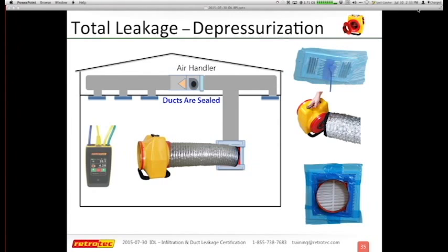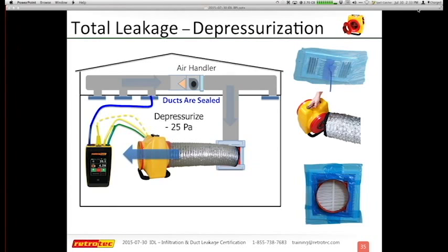You connect your gauge. There's a blue tube that usually goes to the register nearest the air handler. It doesn't have to be, and your goal is to make sure that you're getting pressures further away from the system, to make sure there isn't anything clogged or a significant issue. Connect your tubing and speed controls to the system itself, and you depressurize to 25.